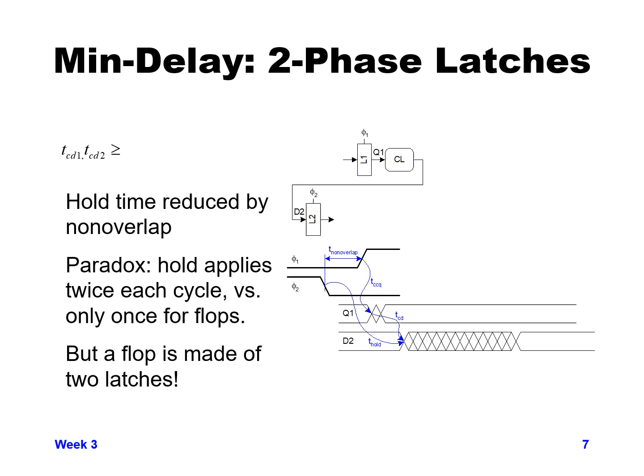This is followed by the delay through the combinational logic from Q1 to D2, and we want to know the contamination delay, the fastest delay through the combinational logic. So when we add those two contamination delays together, that's the total contamination delay. Now again, that needs to be greater than the hold time from the phase 2 latch.